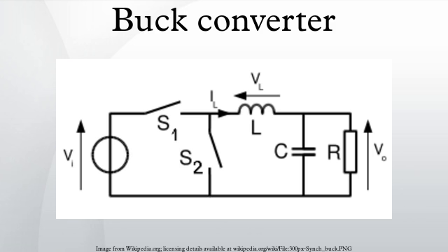In the on state, the current is the difference between the switch current and the load current. The duration of time is defined by the duty cycle and by the switching frequency. For the on state. For the off state. Qualitatively, as the output capacitor or switching frequency increase, the magnitude of the ripple decreases.